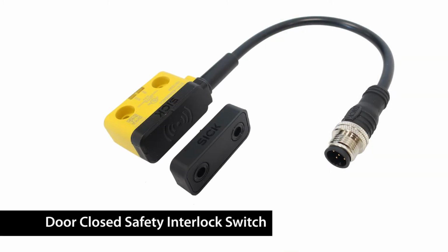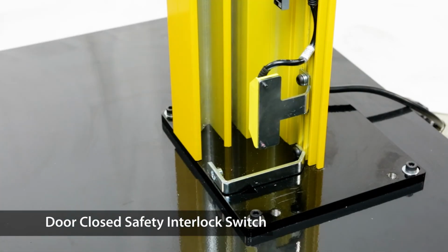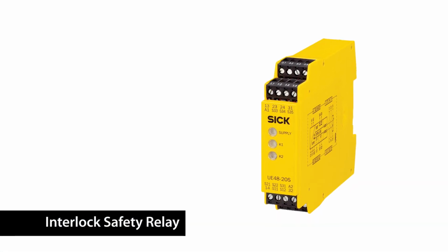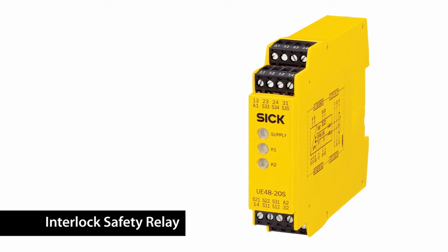The door-closed safety interlock switch option helps meet PLe Category 4 safety requirements when combined with appropriate logic and conformance to risk assessment. This switch provides a confirmation that the door is in the closed position. The interlock safety relay connects to the door-closed safety interlock switch or can be integrated into your existing safety PLC. Other relay switch brands could be requested but should be evaluated by Dynatect prior to ordering.